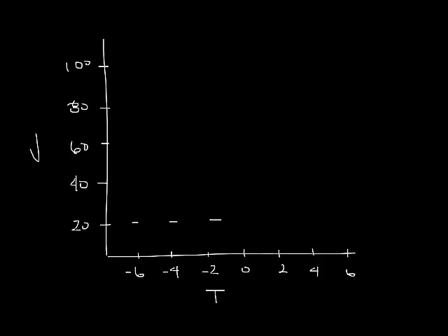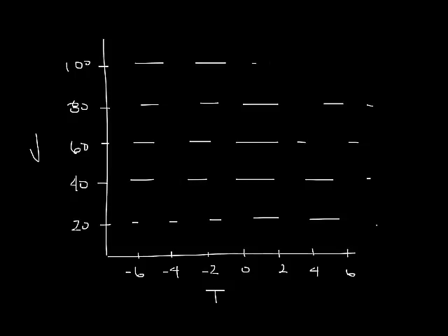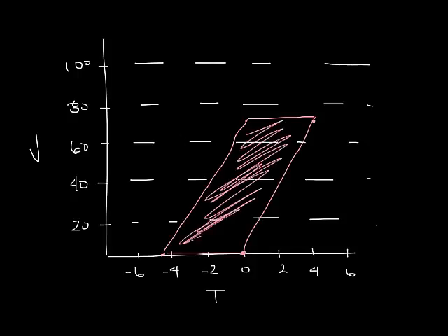Okay, so let's draw a graph showing temperature and velocity. Across the bottom is temperature, and it's actually the differential temperature Tx minus Tc from our equation earlier. And up the side is velocity. We'll draw those in. Draw some lines so we can kind of see. Okay, now if you look at the point where the effective draft temperature would be -3 or up to +2, you can draw in these points and you can see it forms a parallelogram. Let me color it in a little bit so it's a little easier to see.